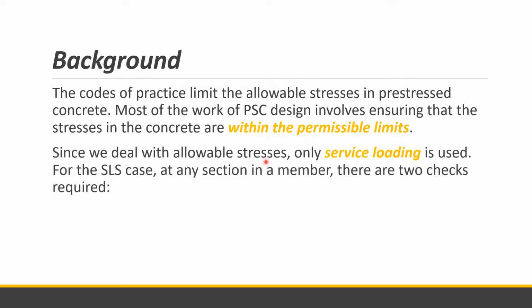Since we deal with allowable stresses, only service loading is used. So yan yung mga live load, dead load, yung mga additional. Yung other loads hindi na siya kasali, like mga wind load, earthquake load, hindi na siya kasali dito sa design ng pre-stressed concrete. So for a service load na case, at any section in a member, there are two checks that are required. Merong dalawang consideration na required in the design.